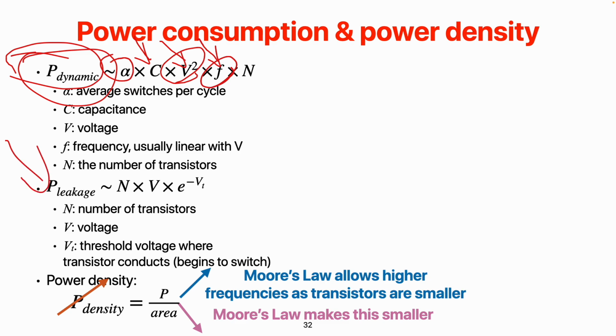And the other power is called leakage power, or static power. One thing you need to be aware of is that nothing is perfect. Every transistor will potentially leak electricity when it's connected to electricity. So whenever you power on your transistor, it also starts to leak some electricity because of the imperfection of your material. And the leakage power is also related to your voltage supply.